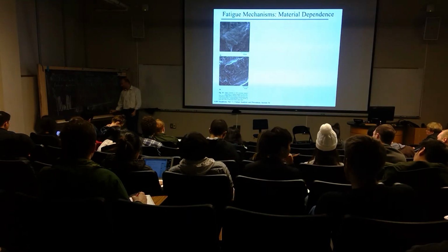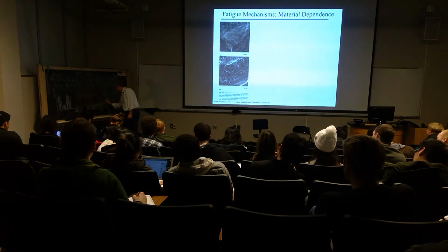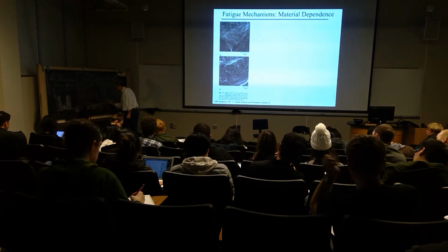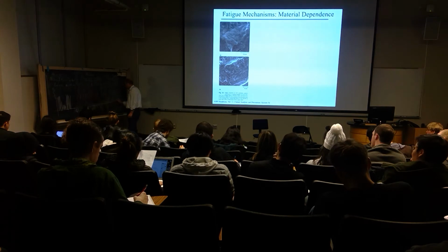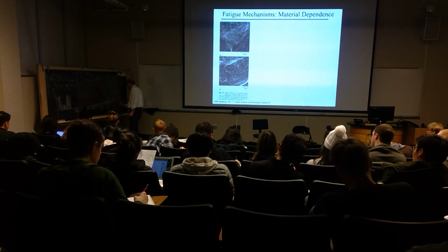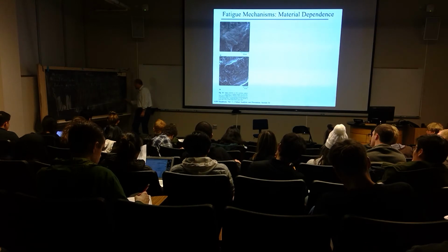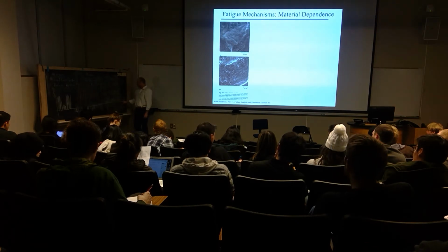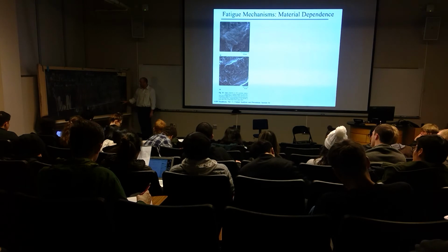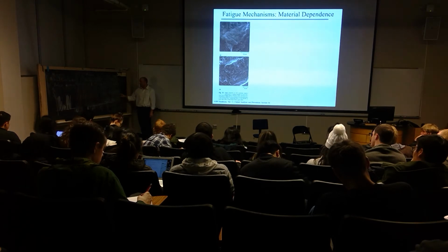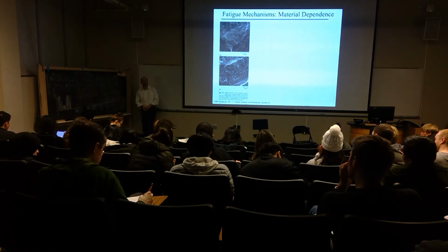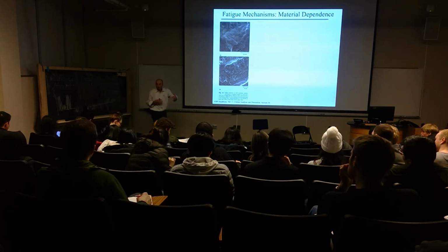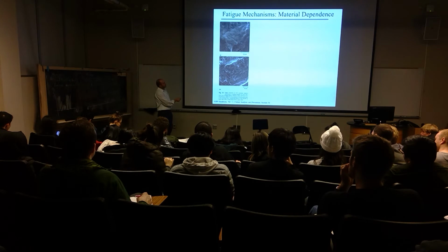You're waiting for your K max, which is F S max square root of pi a sub c, to equal K1C. So we wait until the crack grows long enough that it actually results in fracture. But in all this time, the crack is gaining driving force, and so it should be extending a longer and longer distance in each cycle. And you can actually see that.